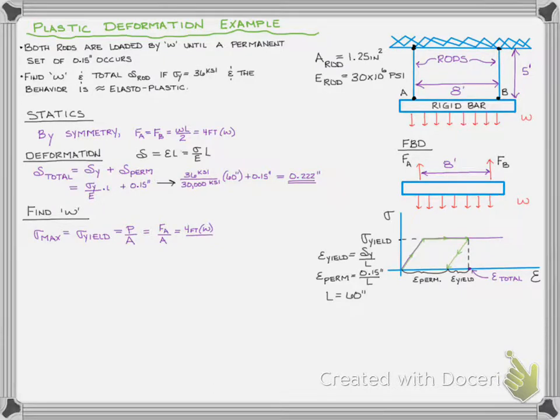That's going to be FA or FB, and so we can just divide that by the area and set that equal to the peak stress. This only works because we yielded, and in an elasto-plastic material, once you're told you've yielded, you know the stress. I cannot emphasize this enough.